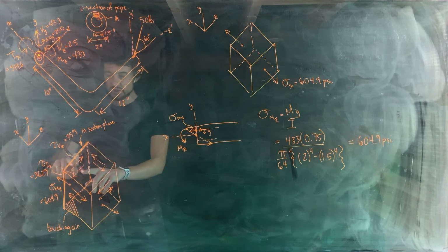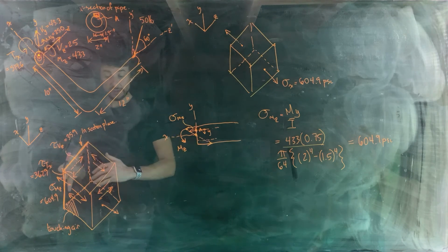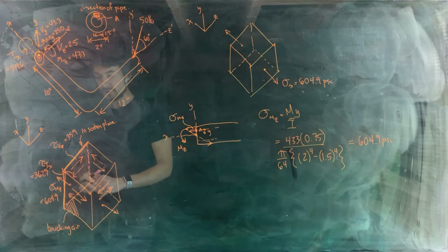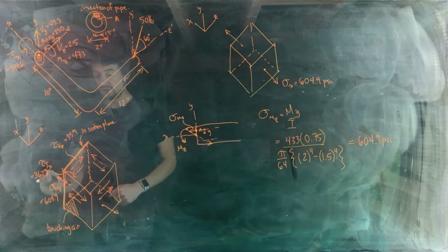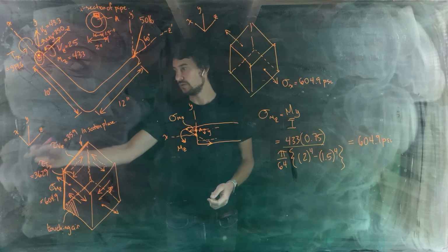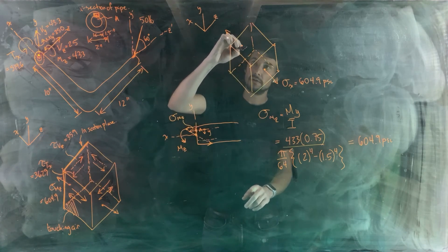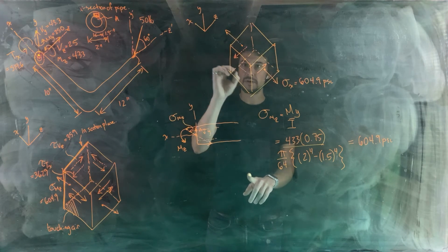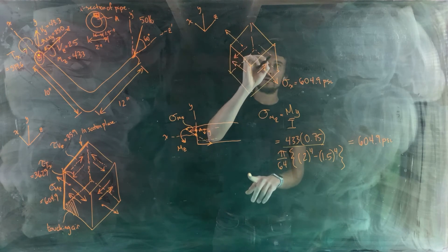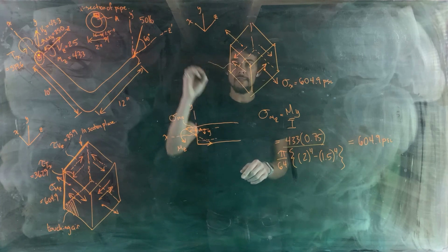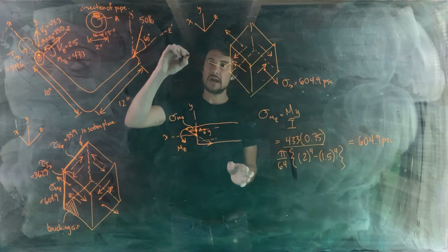Now we've got two shear stresses. They're parallel to each other, so they can be combined, but pointing in different directions, so we want to take the difference. The one with the larger magnitude gives the overall directionality of the shear stress that we want to include on our pictures. So that's in the direction of tau tx, which is the negative z direction. There we go. Let's put in the other shear stresses we need to put in.